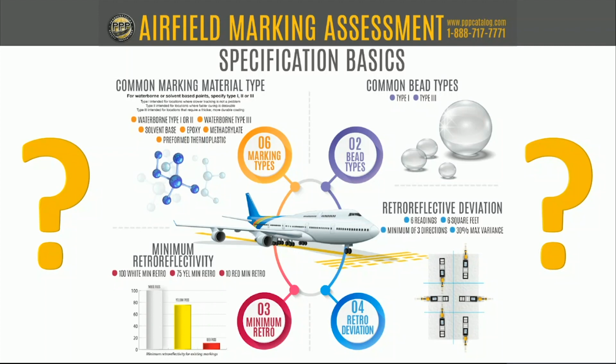Thanks, Greg. And that's a very good question. And I think just to clarify, the graphic actually shows a reflectometer measuring in what appears to be 3 directions there, not only in an upward direction and downward direction, but from side to side. So I guess technically 4 different directions. The intent is to measure in the direction of travel and in the opposite direction of travel.